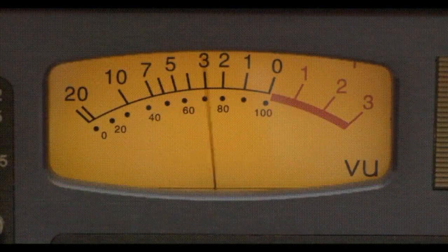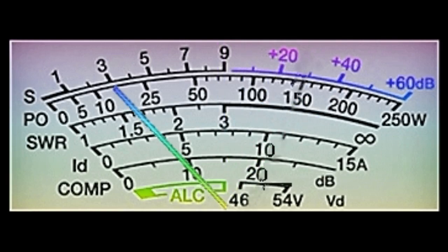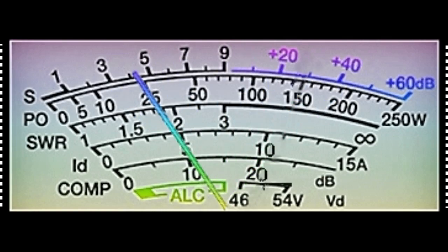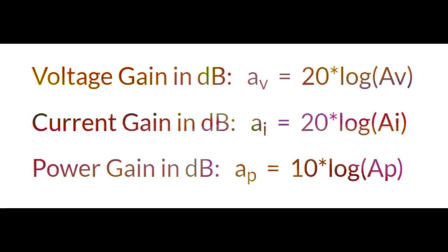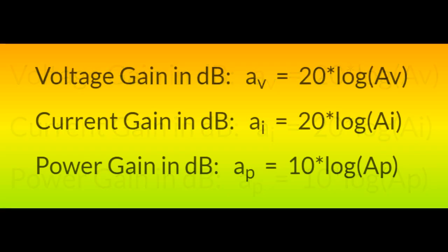Amplifier gain or power is expressed in decibels or dB. Bel or B is a logarithmic, base 10 scale of measurement that has no units. Since the bel is a very large unit of measurement, it is converted to decibels with the prefix deci, which is 1/10 of a bel. To calculate amplifier gain in decibels or dB, these expressions can be used.